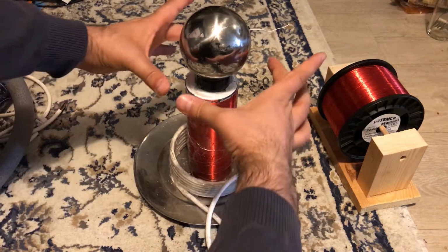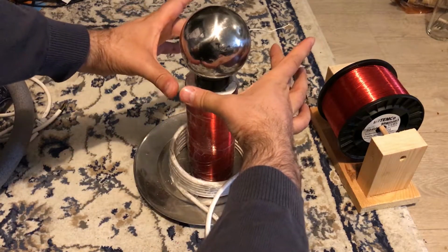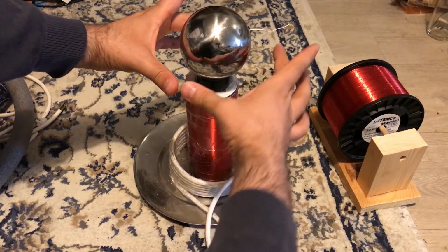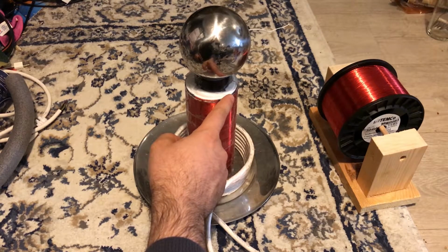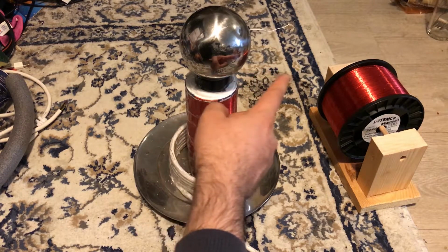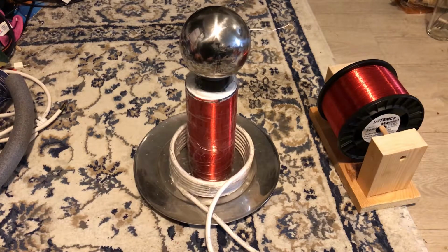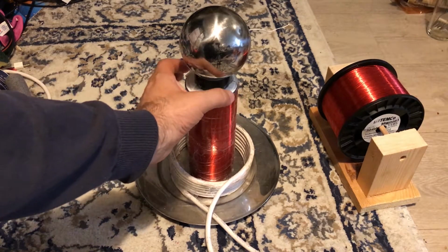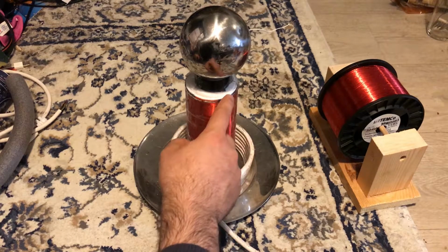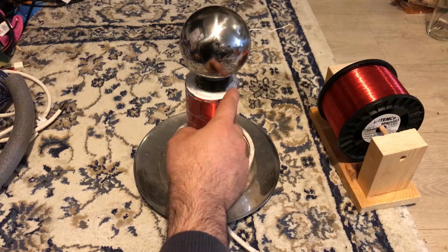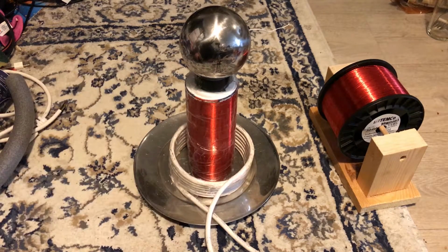However, if we use a toroid, it is equipotential, so it's a metal, everywhere would be the same potential. So we see that here we have, for example, the high voltage, and all these regions will also have the high voltage. Because these sharp points are now located at a concave angle, and the surroundings have the same potential, the electric field at those regions will not be very high, so we will not get discharges from these regions.